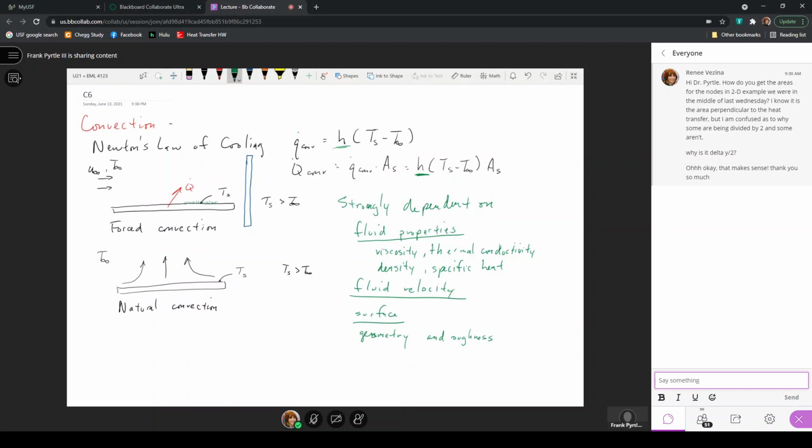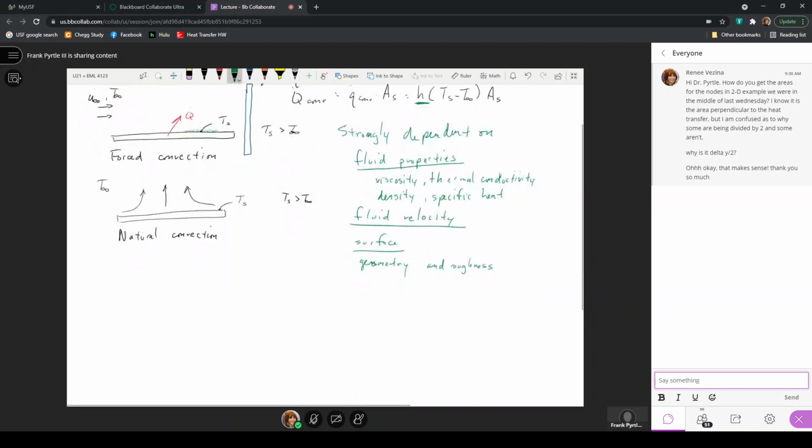And so the dependence of the heat transfer coefficient on fluid properties, fluid velocity, and surface roughness all have to be considered, in addition to, finally, the type of fluid flow. And we only use really two types for flow over a flat plate. The flow types that we'll consider come from the hydrodynamics of the problem, which is laminar and turbulent, or let's say laminar or turbulent flows.